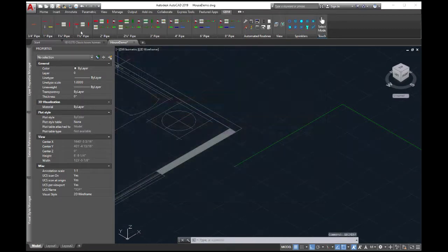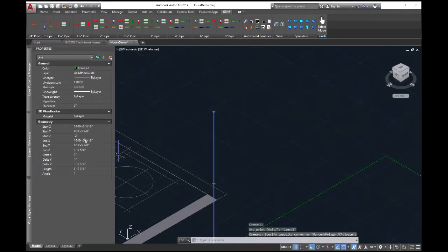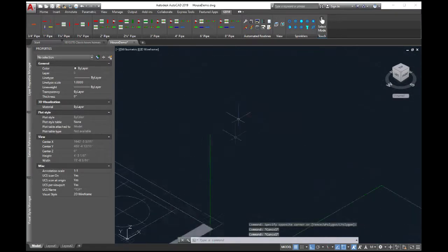So what we can do is once again draw our 1¼ grid line, grab this guy, and we'll come up to, usually what I do is I just come up somewhere and stop, and then I can look at where I ended for an elevation, and I figure I want to be approximately, let's say 2 feet above ground. So now we're 2 feet above ground. We started out below ground, right? And then now we're going to have this particular case.